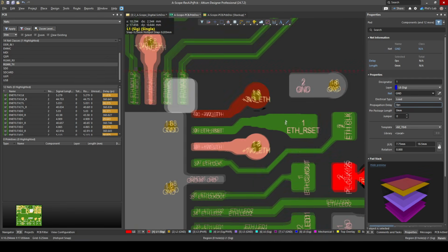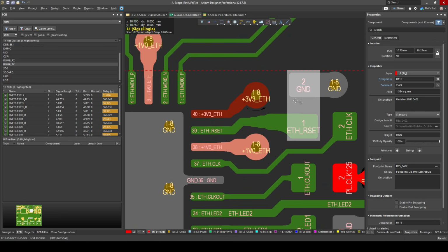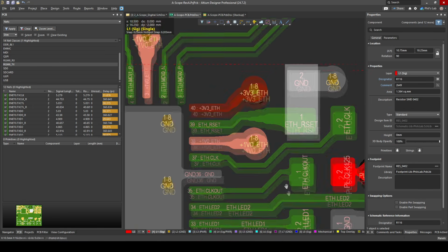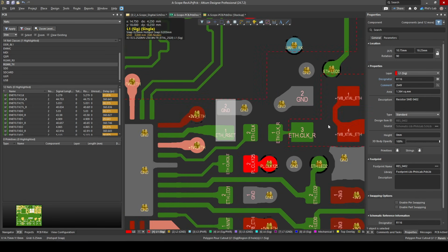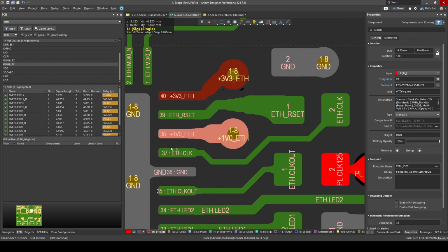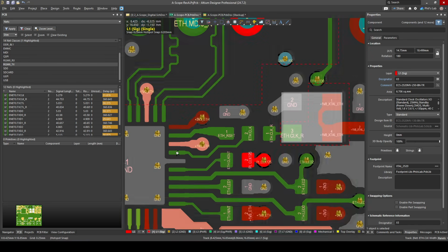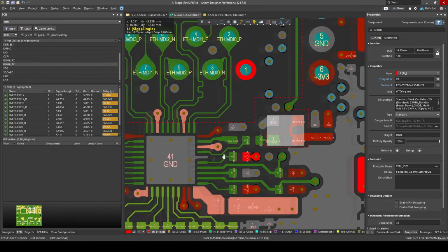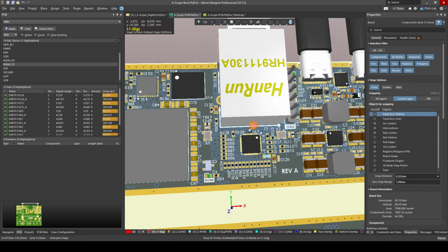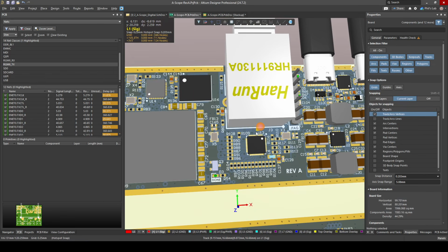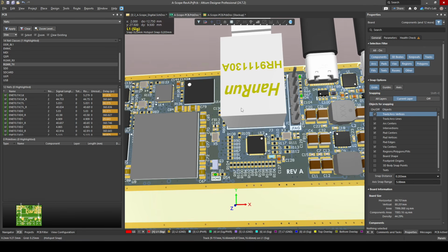Other peripheral components, such as the bias resistor, I also try to place close to the device because these are fairly important, as well as, for example, the crystal CMOS oscillator that's driving the 25 MHz clock on pin 37. I try to keep that close to the physical layer itself. But overall, there's not too much to the PCB design other than keeping controlled impedance, placing your series termination resistors as close as you can to the relevant driver outputs, keeping reference grounds close, adding transition and transfer vias, and if you can, using MagJack connectors because that makes your life quite a bit easier.